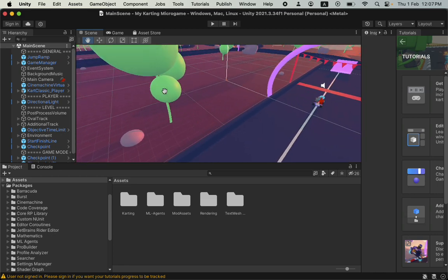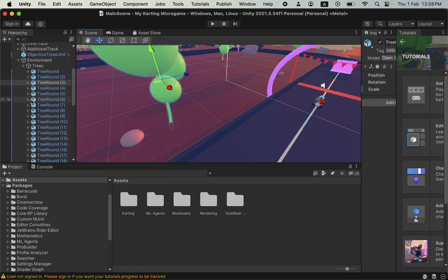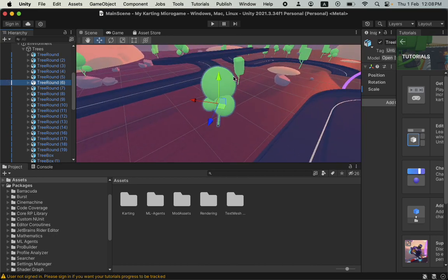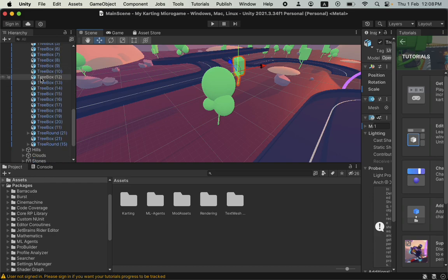Or you just consider a tree like this. Okay, so let me select the tree, and now you see in the left hierarchy this branch got expanded, right? So this particular tree you have selected, that's why this branch got expanded, and it is also showing which tree you selected in the hierarchy panel. Okay, if you select a different tree, it is somewhere else in the scene, so you can go to the tree by pressing F. All right, or you select this tree and this hierarchy panel will also change. This is this tree box.